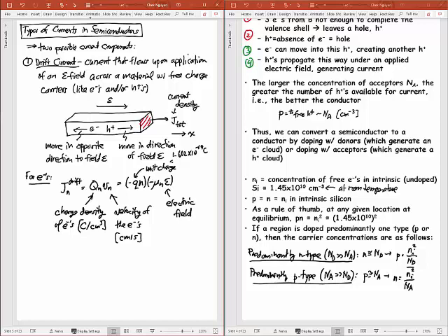And so what is mu n? Mu n is equal to, by definition, what's called the mobility of electrons in silicon in this case. And so there are all sorts of mobilities. And so the mobility of electrons in silicon, at least at a certain temperature and for reasonable doping concentrations, and I'll tell you what reasonable means later on, is on the order of 500 square centimeters per volt second. Okay? And so what is mobility?